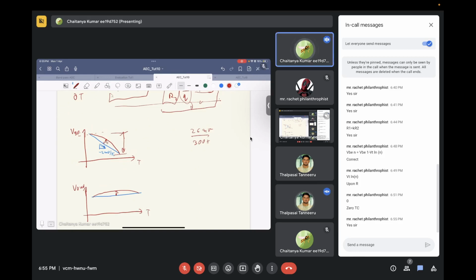Can we design a band gap in fixed GM also, sir? No, fixed GM and band gap are two different things. What a fixed GM circuit basically does is change the current of the transistor in such a way that across PVT, its GM remains constant. That is a different concept.